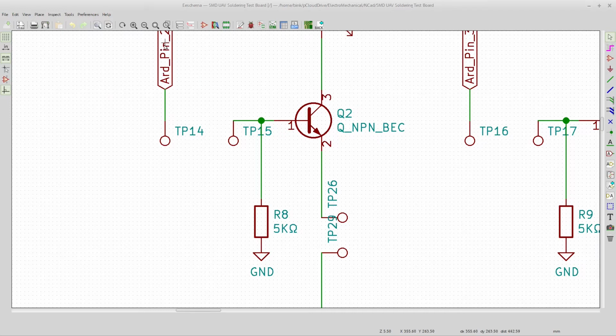When we turn on the Arduino pin and that voltage comes over to this pin, like I said, it turns it on. When we turn it off, when the Arduino says off, you can end up with a little bit of electricity on this wire right here. And that small amount of power can cause this pin to stay on. You see what I'm saying?